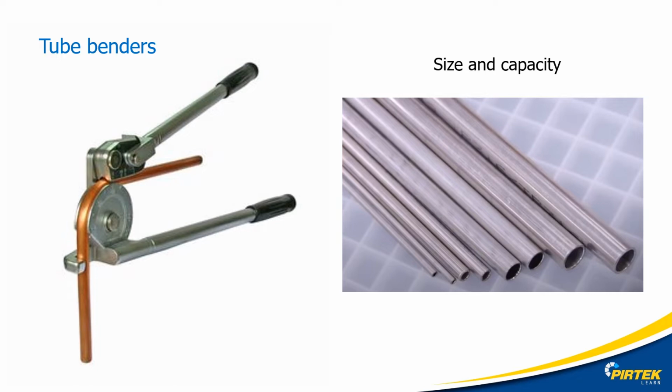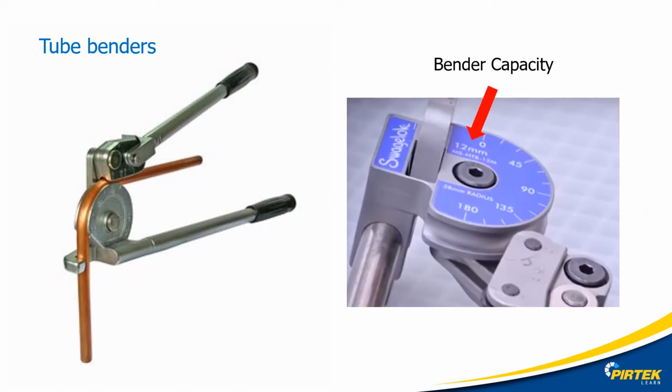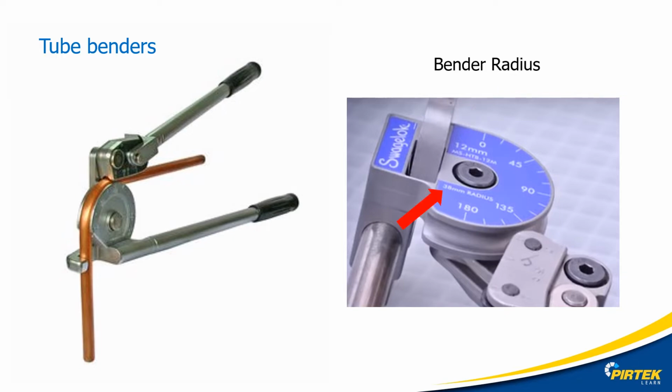There is a vast variety of tube benders on the market, cheap generic units and quality units. Irrespective of the quality, it's important to determine the maximum tube size, the bend radius, and if it's capable of bending your particular material. Check with the operators or user's manual that come with the tube bender. Most benders will come stamped with a maximum tube diameter and bend radius. These dimensions are important because we use them to calculate the bend allowance.